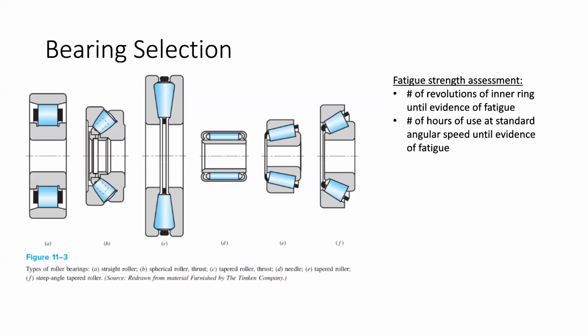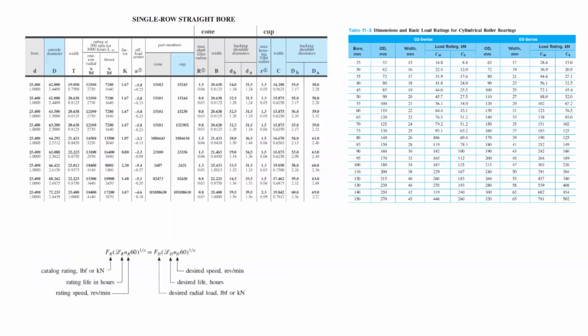So the evidence of fatigue that you typically see in something like a bearing failure is what they call galling. You have debris that builds up in the bearing as you damage the surfaces, and over time, this results in damage of either the cup or the roller elements to the point where they don't function anymore. Foreign debris, I guess, isn't really something that they do, but these are relatively standard tests that the bearing manufacturer carries out. I don't know exactly how they inspect it, but the idea is that you just stay under their load rating and you should be fine.